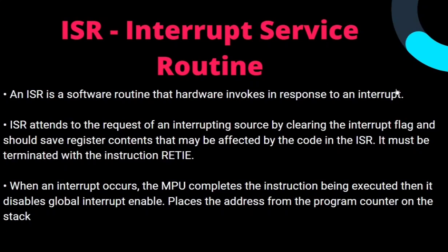When an interrupt occurs, the MPU completes the instruction being executed, then it disables the global interrupt enables. And then it places the address from the program counter on the stack.